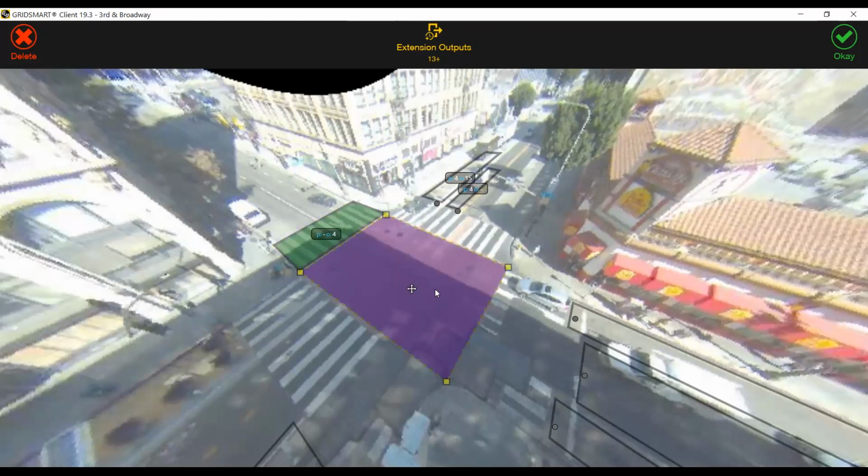If you needed to count PEDs, you can draw a vehicle zone in a crosswalk, but I will highlight that at this point in time, our system does get confused with groups of PEDs moving in the same trajectory and may only count them as significantly less than they're actually in the group. You might get a group of 3 or 4 be counted as 1, but you would have to draw a vehicle zone even to get that count.